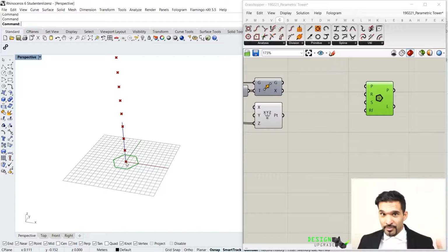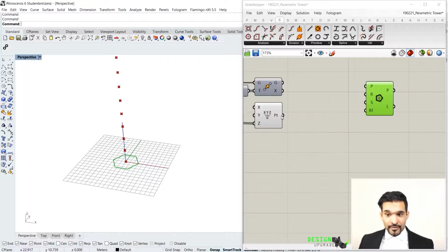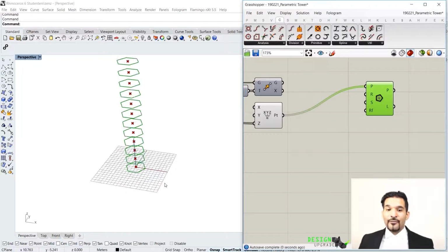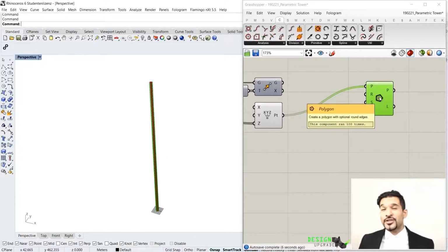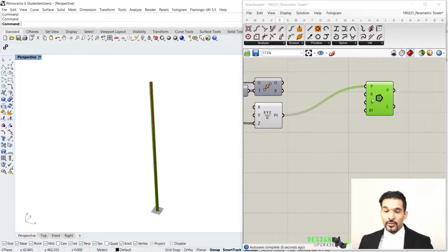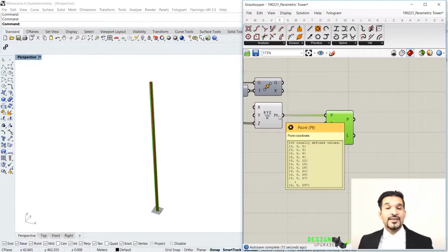That's my world top XY construction plane. If I now put in the points that we constructed before into my P, I will supply a different list of planes that those polygons are being drawn on. So instead of 1, I will get 200 automatically just by supplying a list of different planes, which are translated here by the input of points.